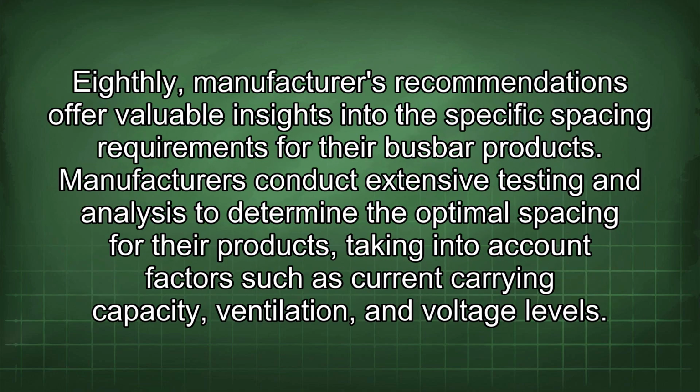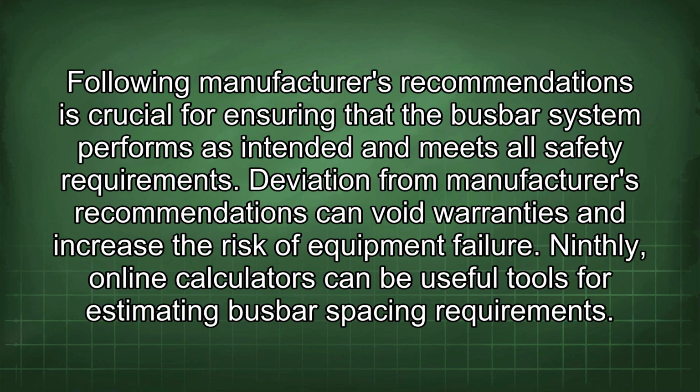Eighthly, manufacturers' recommendations offer valuable insights into the specific spacing requirements for their busbar products. Manufacturers conduct extensive testing and analysis to determine the optimal spacing for their products, taking into account factors such as current carrying capacity, ventilation, and voltage levels. Following manufacturers' recommendations is crucial for ensuring that the busbar system performs as intended and meets all safety requirements. Deviation from manufacturers' recommendations can void warranties and increase the risk of equipment failure.